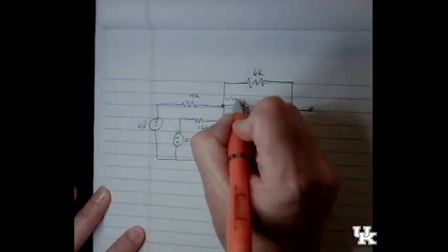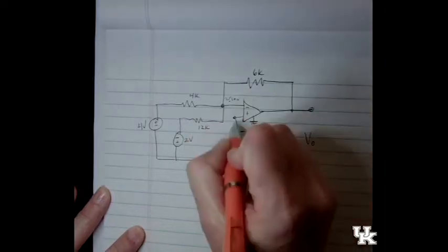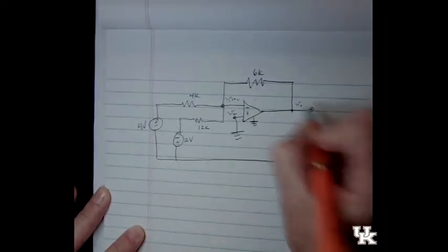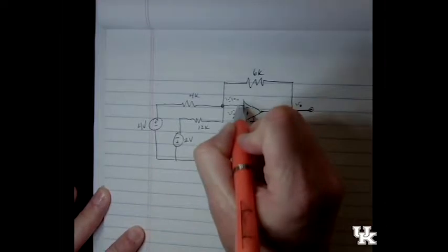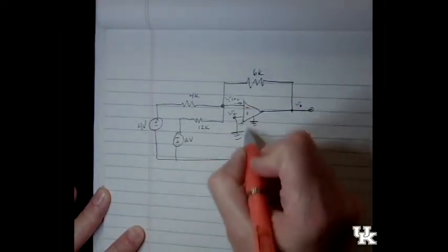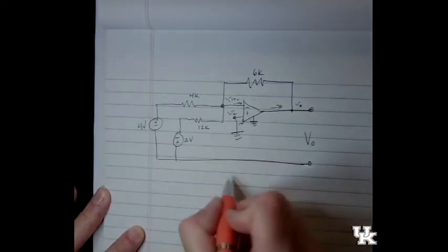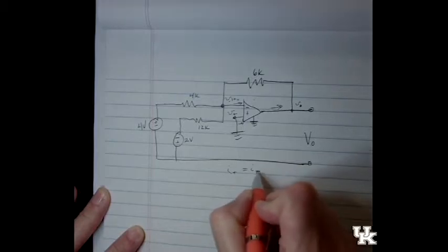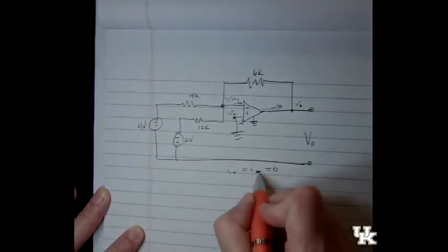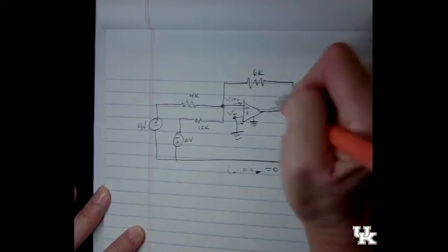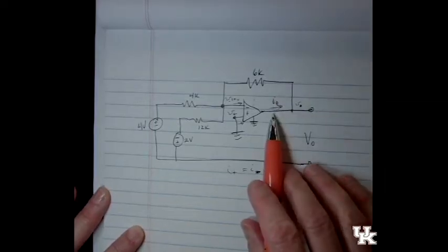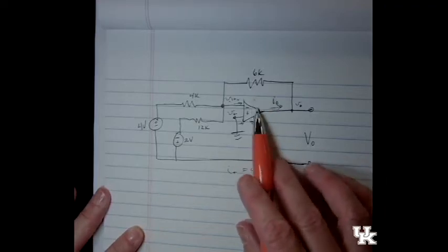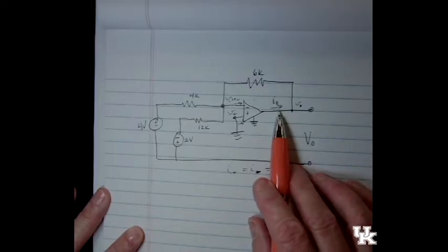voltages, the inverting we'll call V minus, and the non-inverting V plus, and the output is V out here. And then the current associated with each of those, and my drawing's not really big enough, the current there, I plus and I minus, we assume by our model that those are equal to 0. But the current coming out can be whatever it needs to be. And that's because of that other source that we're not even drawing. That source is providing power that's producing this output current.